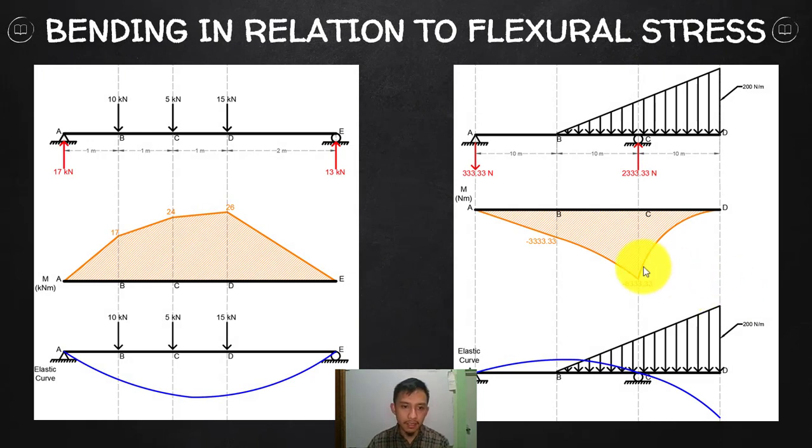So for example, look at this beam. We had this one in your examples in module 4. This is now the moment diagram. For you to draw that, you can take a moment at any section and draw your moment diagram directly, no problem, you do not need to pass through your shear. But if you still cannot do this directly, then you should go through your shear and moment diagrams. So these are the moment diagrams of our previous examples.